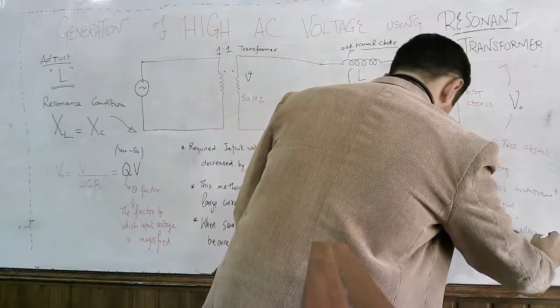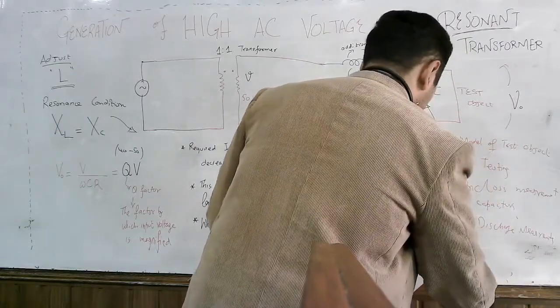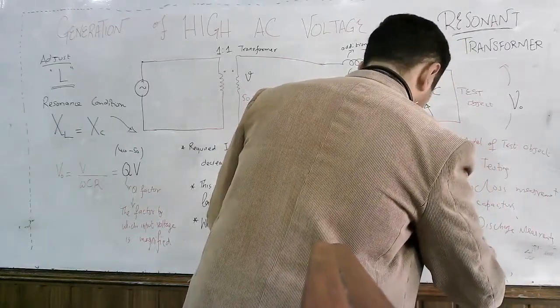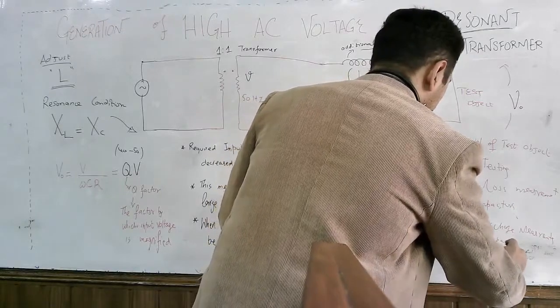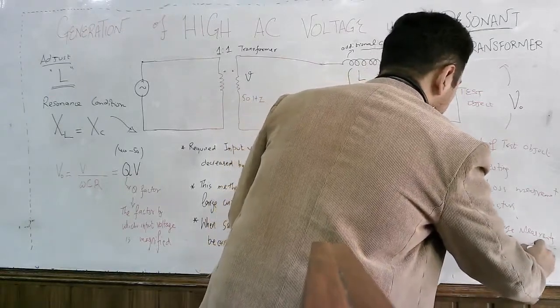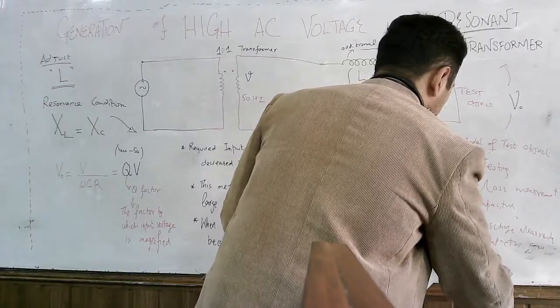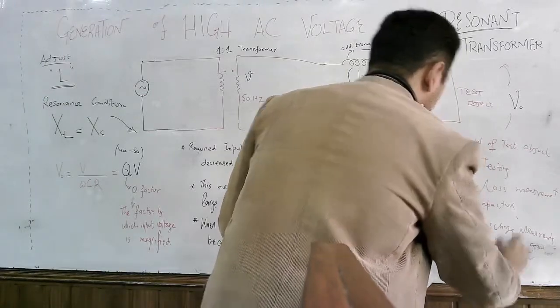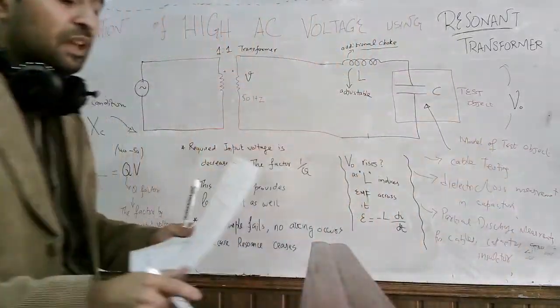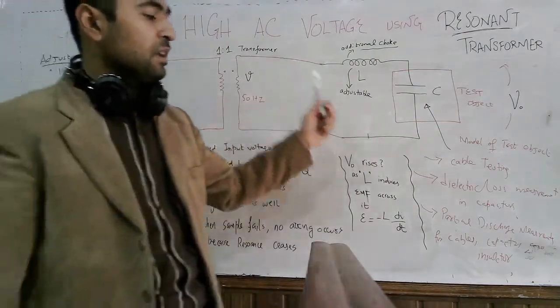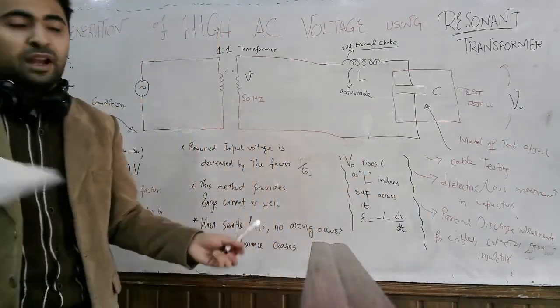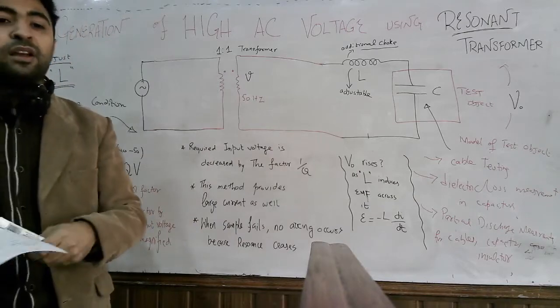Partial discharge measurements for cables, capacitors and insulators. So this type of topology finds three applications: cable testing, dielectric loss measurement and partial discharge measurement.